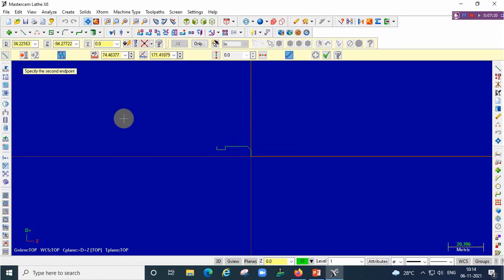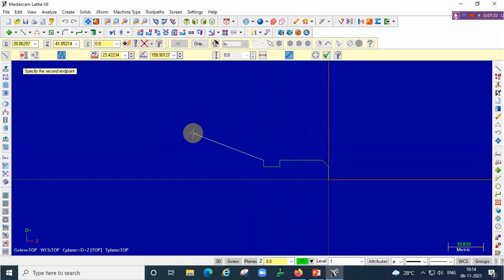Say one grooving is completed now. We have one slanting line, 20, minus 25, 20, minus 35. One more groove we have, 15, minus 35, 15, minus 45, 20, minus 45. Two groovings completed. We have one horizontal line here, 20, minus 55. We have a slanting line here for creating the arc.